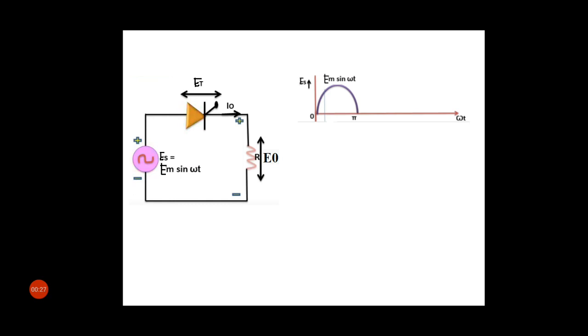See, this diagram is a single phase half wave controlled converter with R load. We have already discussed this. At omega t equal to 0, when the supply voltage becomes positive, the thyristor T becomes forward biased. However, unlike a diode, it does not turn on till a gate pulse is applied at omega t equal to alpha.